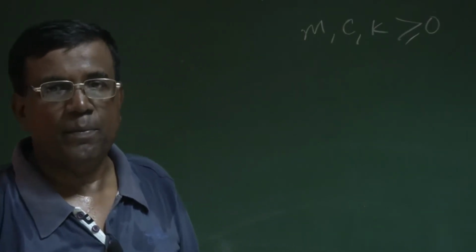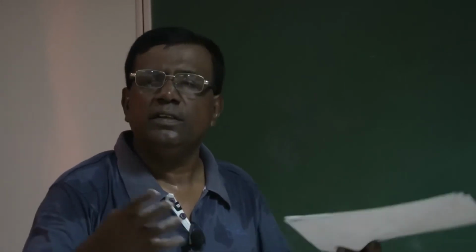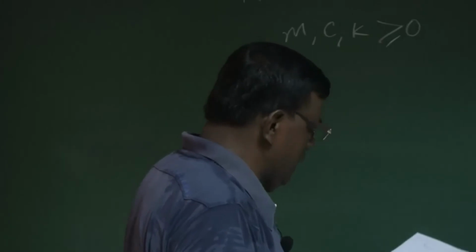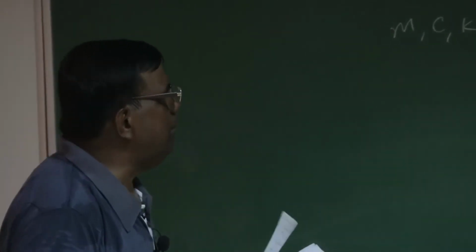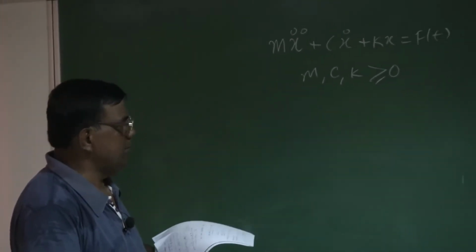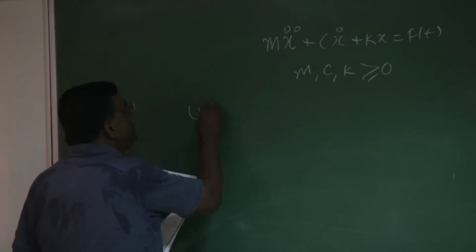All such things we do. But a normal spring mass system will have a natural damping because it is in a medium. Okay, right? So these two understandings were required. And now we would like to check whether a mass spring damper system necessarily means it will always be an oscillatory system. So let us take the first case, under damping.